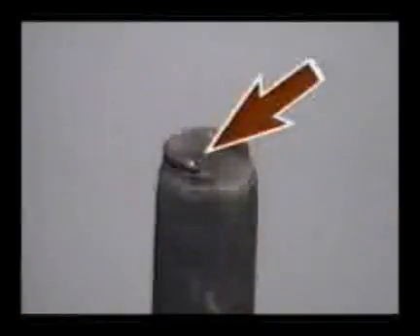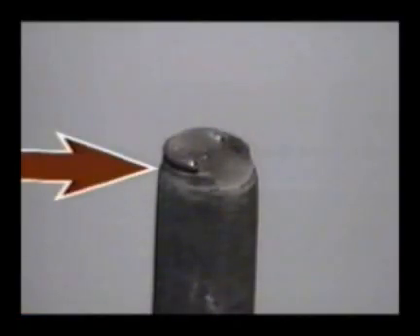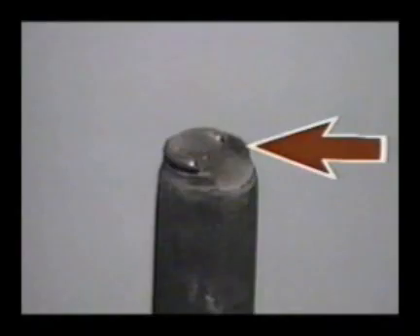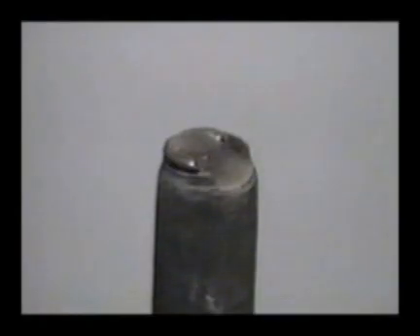If you observed a rough fracture surface, plastic deformation, and shear lips, you correctly identified this as a ductile fracture. You probably could not find an initiation site, so a large abnormal stress raiser is ruled out. Assume the bolt had the correct head markings. Also, there are no temper colors. These facts indicate the material was the right strength and was not weakened by excessive heat. These observations tell us the fracture was probably due to an overload condition, and the bolt fracture is resultant damage. We should look at the related parts to determine how the overload occurred.